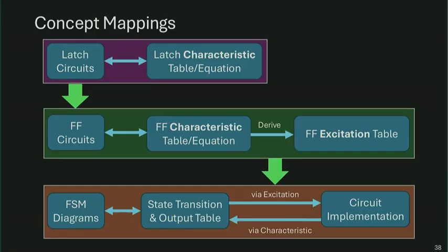And in terms of designing a sequential machine, we need to model the behavior in an FSM diagram, which can also be converted into an equivalent FSM table. And this table, using the excitation table, can be converted to an implementation. We tried that for the T flip-flop, implementing JK using a T based on the excitation table of the T flip-flop. And conversely, you can go from implementation to the table through either simulation or by plugging in the combinational next state logic into the characteristic equation. Right. So that's how all the concepts we learned so far interact.